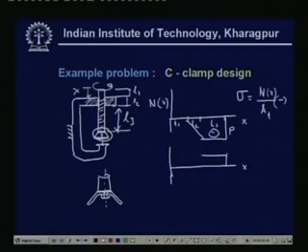Then we have to add the torque, that is the torsion due to the friction in the thread, and that varies almost linearly, and beyond this, that is L1, is subjected to the addition of these two, that is Tc, the collar torque, and Ts, this part. So, therefore, this will be Tc plus Ts, this length.